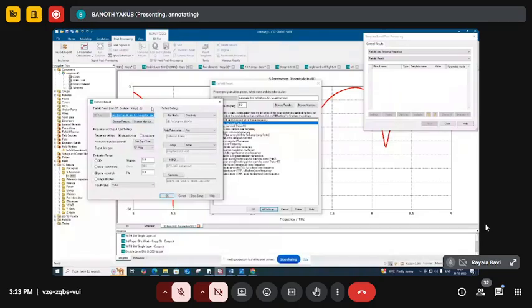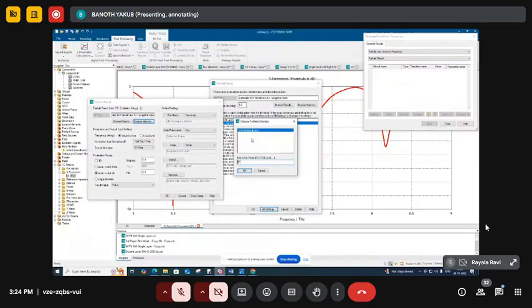So in this far field, after selecting, go to the browse monitors. In browse monitors, we see what far fields we have given for the particular frequency range. For electric field and magnetic field, for a particular frequency, we can give 5 to 9 terahertz: 5 terahertz, 5.5 terahertz, 6 terahertz, 6.5 terahertz. That far field you can give, and you can select the E field and magnetic field. What we selected in the far field will be shown here.